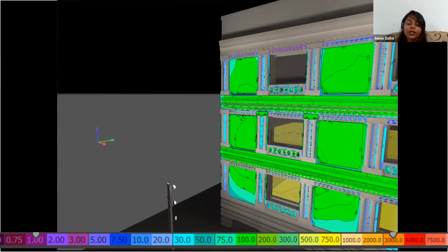And another important factor is the color, texture, and form of the facade, because what we perceive is nothing but the reflected light of the surface. So if you have a very dark color on the facade, naturally, even if you are throwing a lot of lumen on the surface, what gets reflected is very little, because the color of the facade itself will absorb most of the light. So when you're designing, we also need to study the color, the texture and the material of the facade.